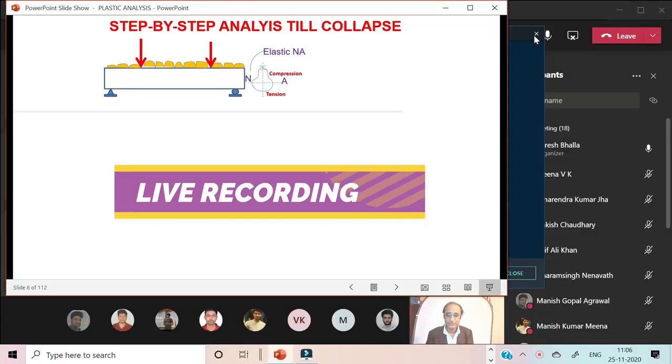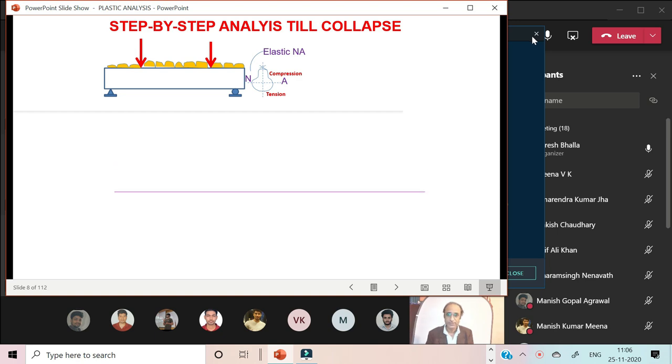Good morning, everyone. We are now continuing from where we left off in the last class in the matter of plastic analysis. Last class we saw the assumptions in our analysis. Essentially, we have idealized stress-strain diagrams. We assume that both in compression and tension, the stress-strain diagram, Young's modulus, and the ultimate strength are all the same. We are also considering a pure elastoplastic model, and there is no strain hardening.